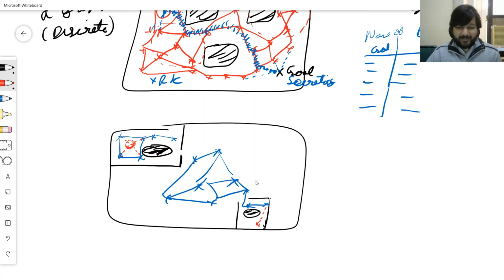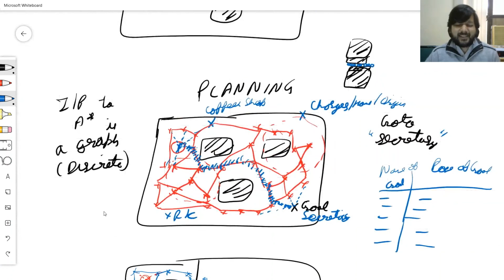And therefore I say that, okay, I'm not getting a path from source to goal. The master has added, so there's probably a path. Then what I do is I try to intelligently find out at which stage I am not getting a path by my graph search algorithm in this region, and here I add lots and lots more vertices. That's not what you would have done if you were going with a discrete A-star algorithm. You would have had to increase the resolution of the entire grid. So here I can just add ad hoc vertices and edges. This technique is of course called the probabilistic roadmap.